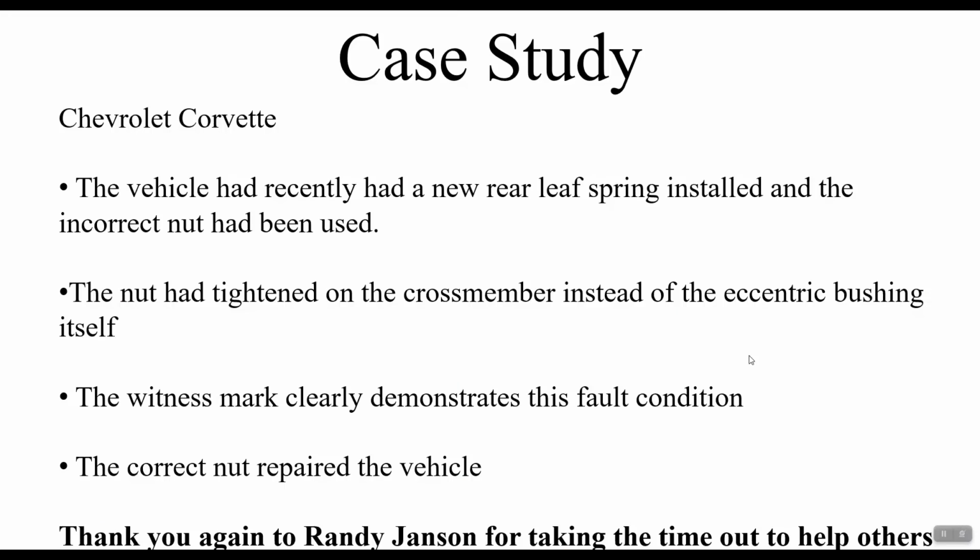Okay, so it had rear leaf springs installed and the incorrect nut had been used. Okay, the nut had tightened on the cross member instead of the eccentric bushing. Witness marks, they clearly demonstrate the fault condition, and the correct nut repaired the vehicle.